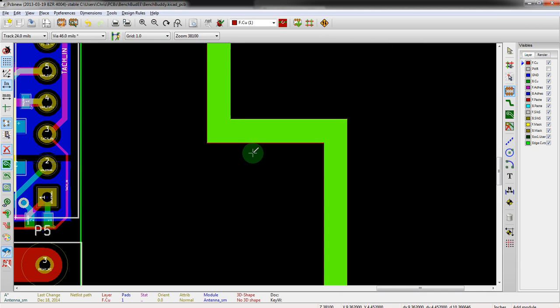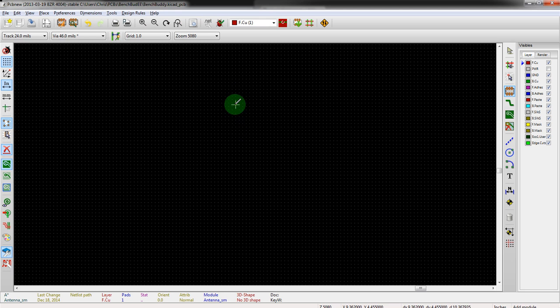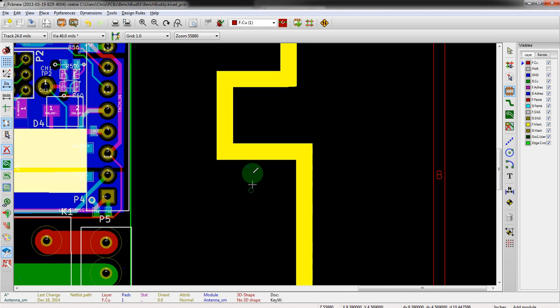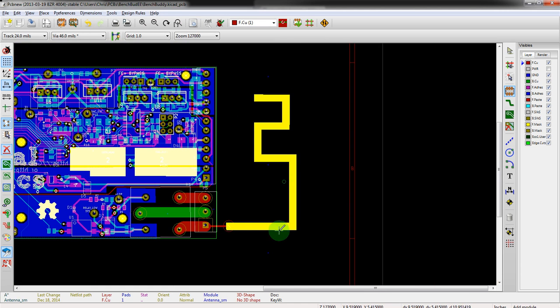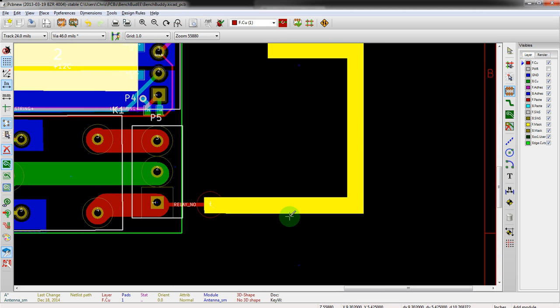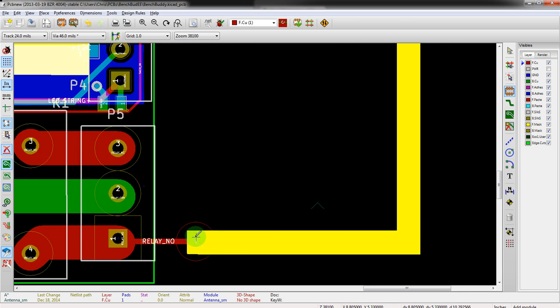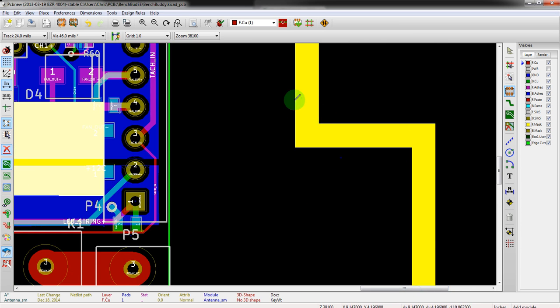Now we can go and line this up. You see that tiny little blue plus there? We want to line those up over top of one another. That's the center point, or the lineup point, for those. Basically what happens now is when you send this to the fab, again, we're outside the board outline, it would relieve all of the solder mask around the copper. So this would all be covered in solder mask over here with a copper trace underneath, and then starting right here, if you needed to, you could have an exposed copper area over top your entire antenna.